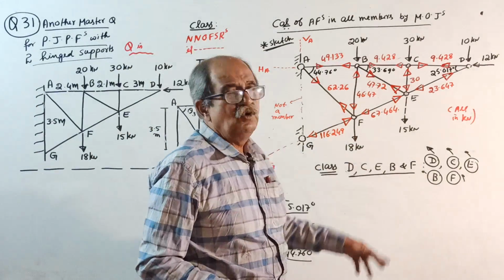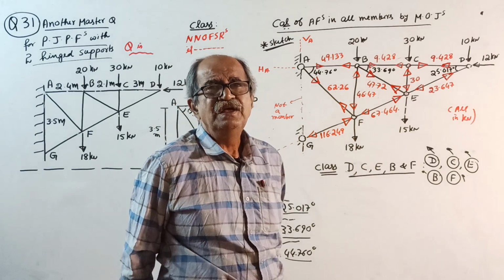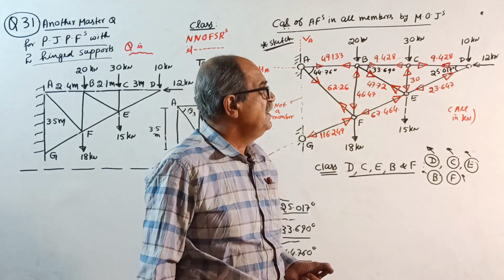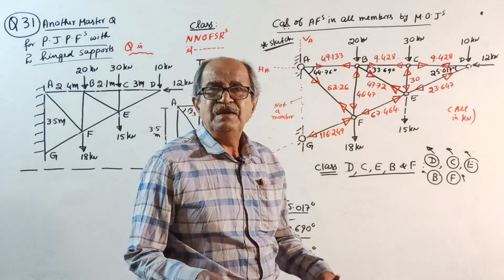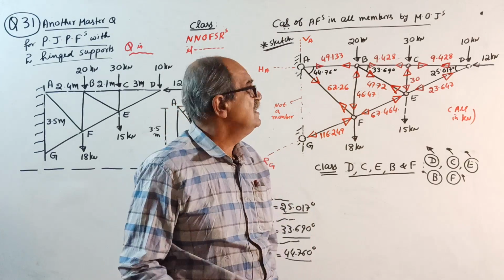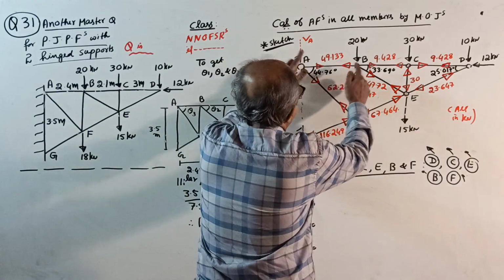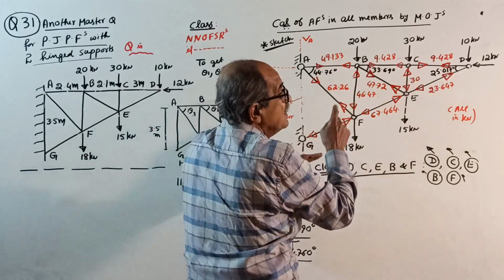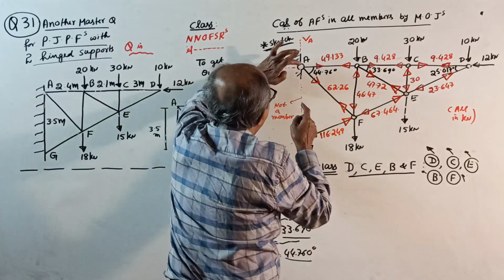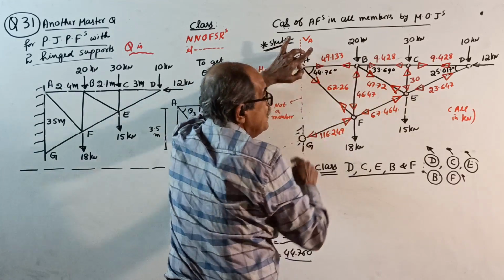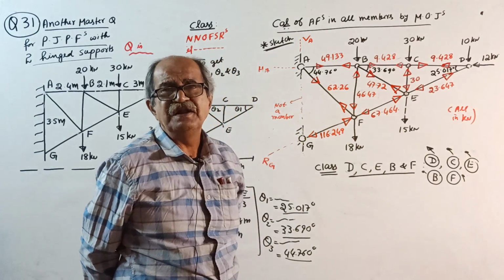Now if you want, you can go for a tabulation, tension or compression. In the beginning I told you it is primary school level. Once you understand how to write it, you will say, oh, I got it. If it is this way, write tension. Someone will say, sir, it's compression. No, it is acting away from the joint. This is all I told earlier.